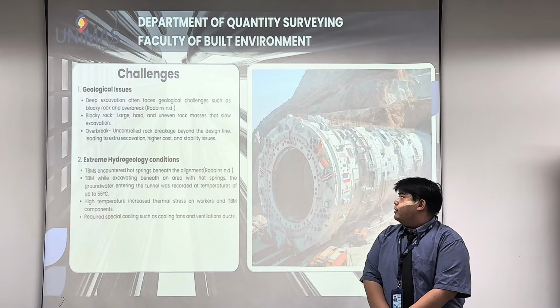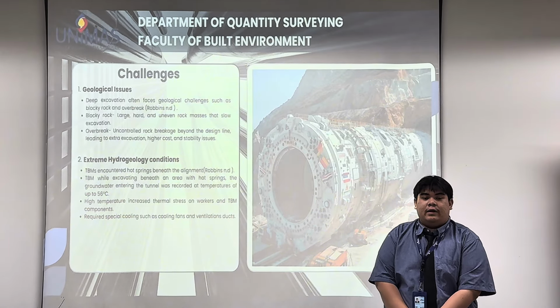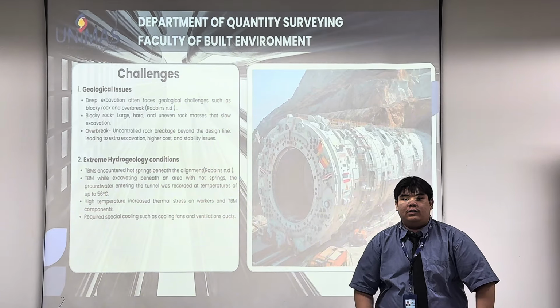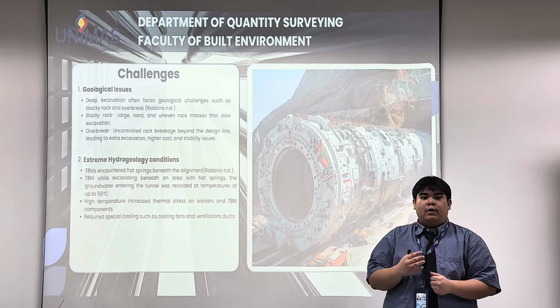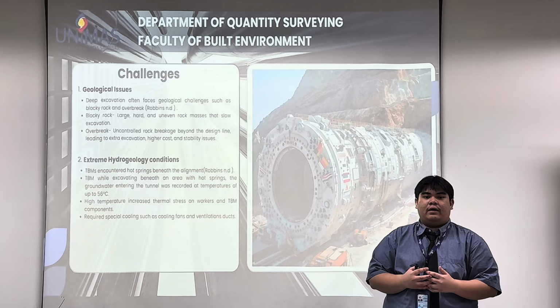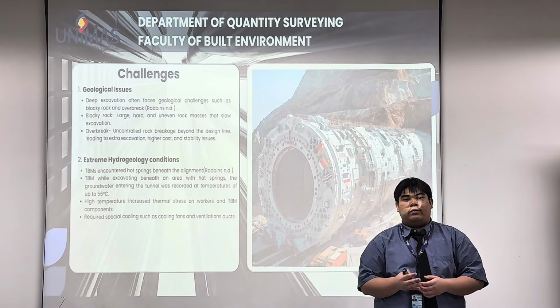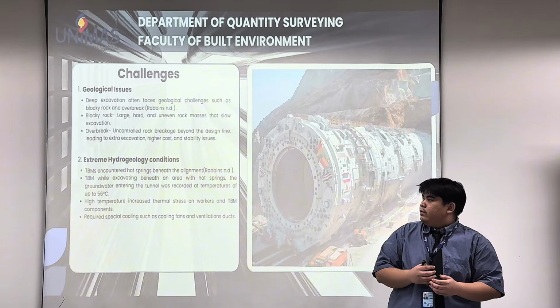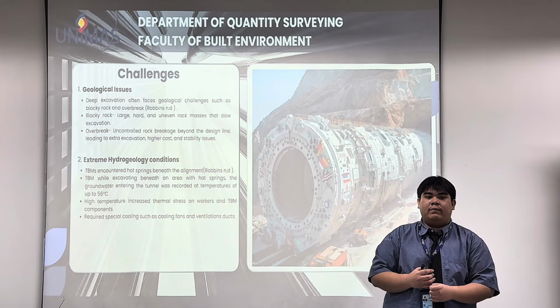Okay, I will explain about the challenges. The first challenge is geological issues. Deep excavation often faces geological challenges such as blocky rock and overbreak. Blocky rock means large, hard, and uneven rock mass that slows the excavation. Meanwhile, overbreak means uncontrolled rock breakage beyond the design line, leading to extra excavation, higher cost and stability issues.